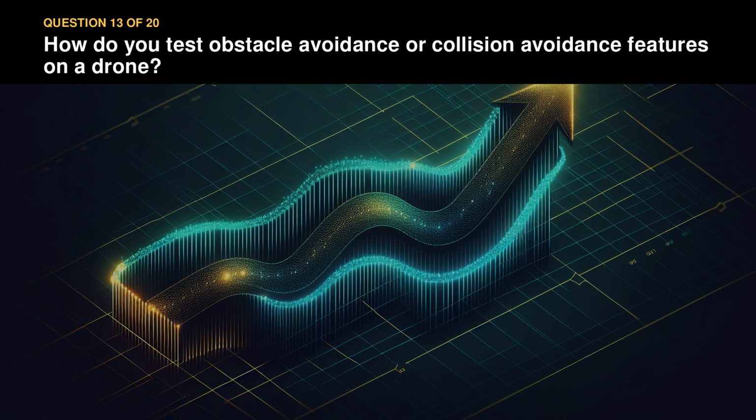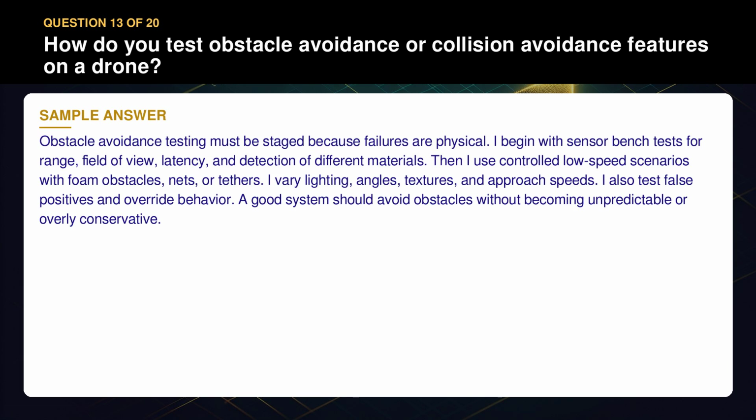Question 13. How do you test obstacle avoidance or collision avoidance features on a drone? Obstacle avoidance testing must be staged because failures are physical. I begin with sensor bench tests for range, field of view, latency, and detection of different materials. Then I use controlled low-speed scenarios with foam obstacles, nets, or tethers. I vary lighting, angles, textures, and approach speeds. I also test false positives and override behavior. A good system should avoid obstacles without becoming unpredictable or overly conservative.